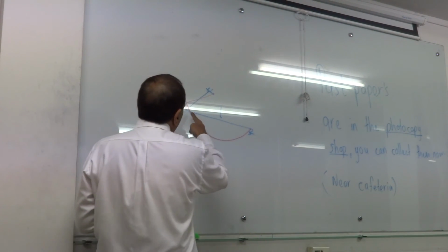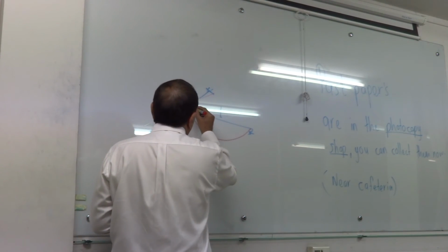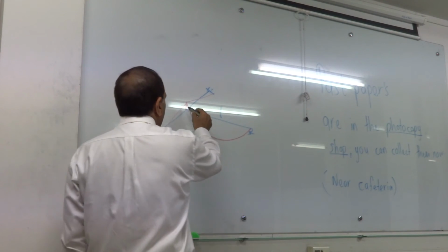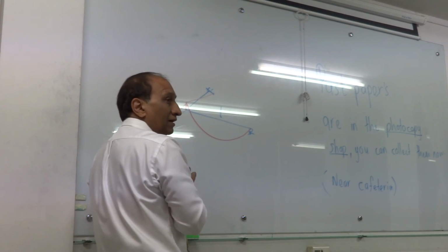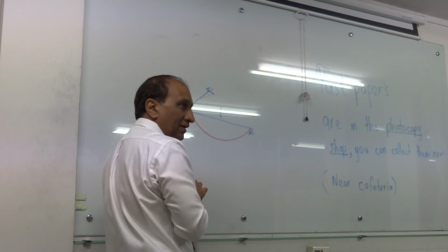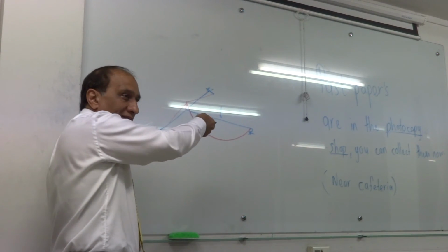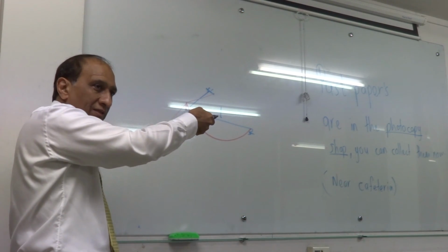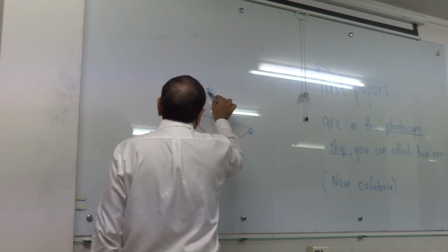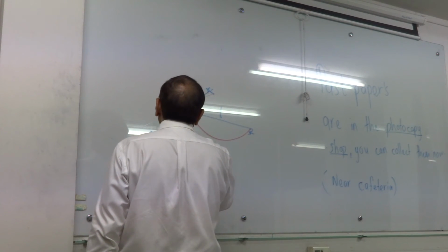So if I apply a load here, there will be a positive moment in this beam, correct? And there is a negative moment because the two beams are connected, and this negative moment will become torsion for that beam, correct? Because they are connected. When this beam deforms, it will twist the beam at the end, and that beam will be in torsion. Now, if this beam fails in torsion here and here, what will happen is that this torsion